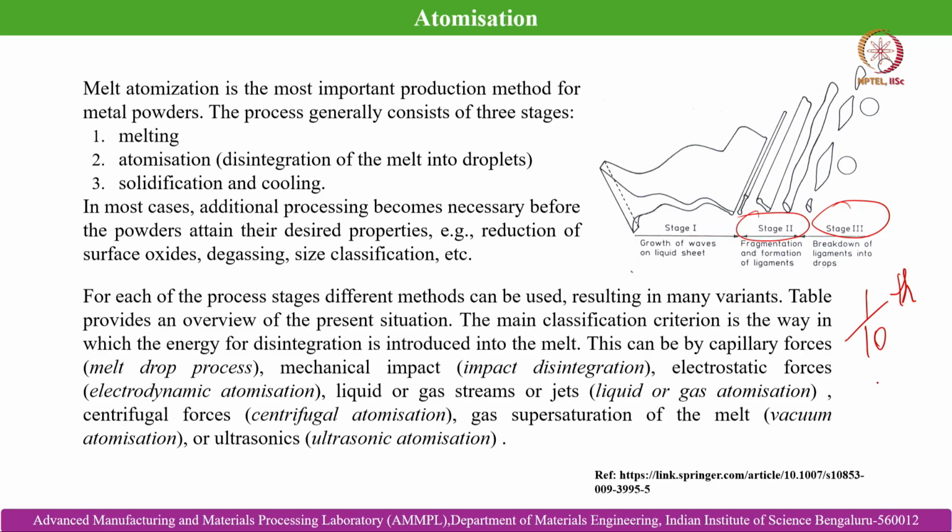So often, if we need to develop features in the micrometer range, then we need to use powder in the range of nanometers. That is also quite common in the medical field, for medical devices. Even similar research is going on in our group. So to develop these nano size powder particles, often we resort to atomization techniques. So what are the atomization techniques, what are their ranges in terms of the powder particle shape that we can achieve, we will learn about it.